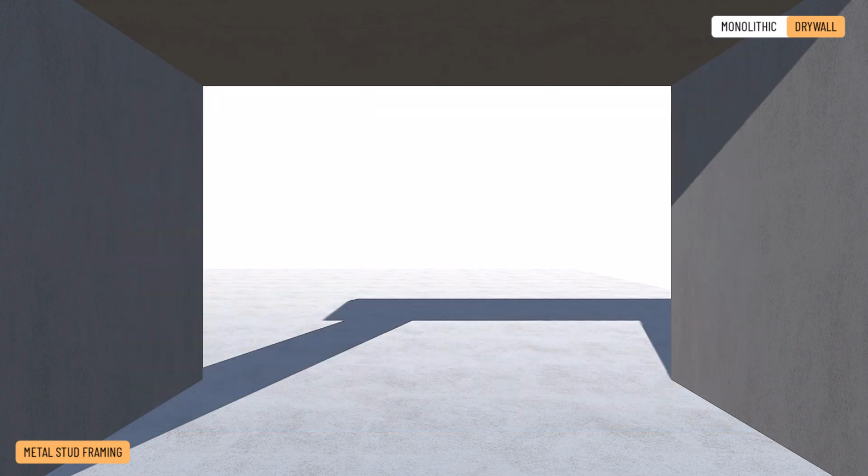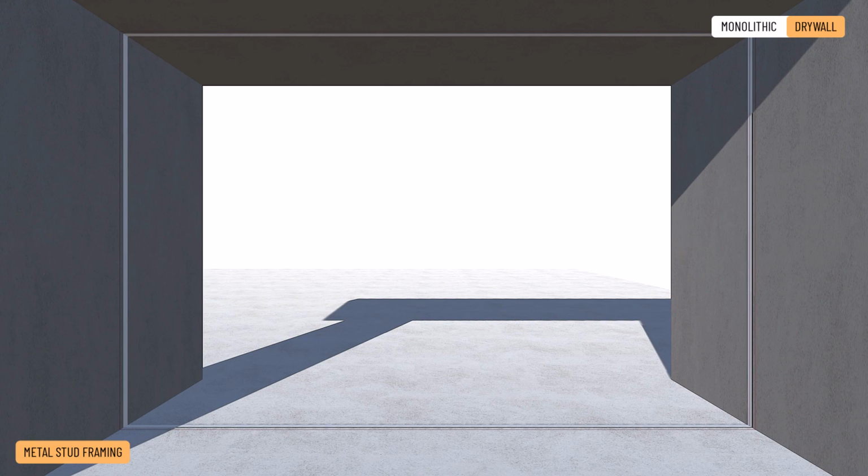1. Construct the metal stud framing partition wall after plastering is completed. We start building the stud framing directly on the screed. 2. During the setting out process, we mark the lines of the walls on the structure, the position of the openings and the connections. 3. First, a self-adhesive sealing and separating tape is put where the elements of the frames will be.